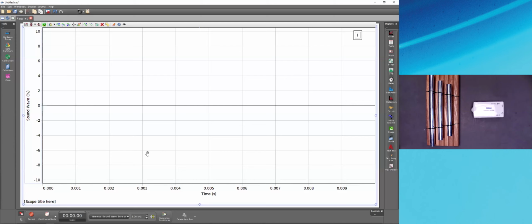The main part of the solution is to recognize that I'm currently in a mode which is the default for new files, called continuous mode. This means that when I hit record, Capstone is going to try to gather data from the sensor at the sample rate continuously with no breaks. In this case, though, I need to go faster than this Bluetooth wireless connection would allow.